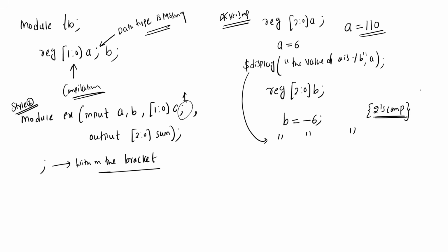In sign magnitude and one's complement, if you want to store plus and minus zero, there are two representations. The compiler can't decide whether to store plus zero or minus zero. But in two's complement, plus zero and minus zero have only one representation. This is a separate topic in digital, about how hardware or a compiler stores a negative number.